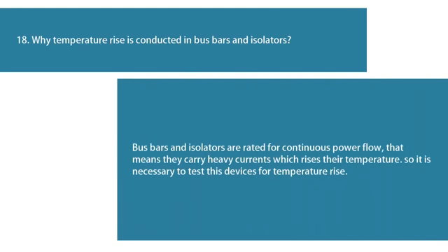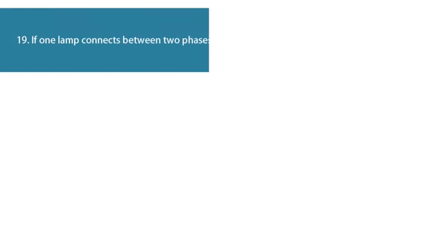18. Why is temperature rise test conducted on bus bars and isolators? Bus bars and isolators are rated for continuous power flow, that means they carry heavy currents which raise their temperature. So it is necessary to test these devices for temperature rise.